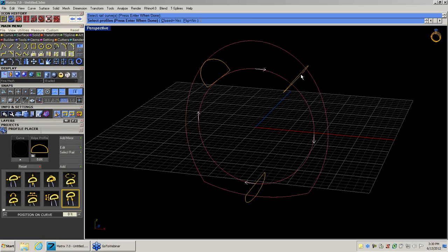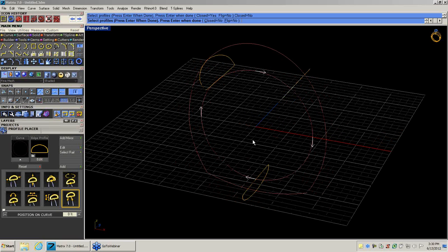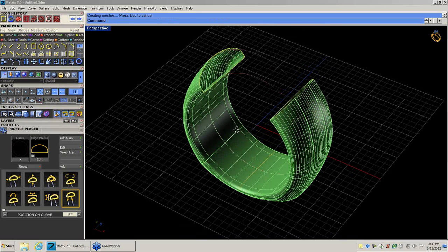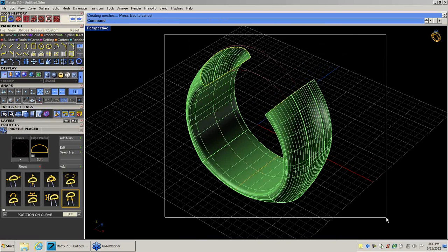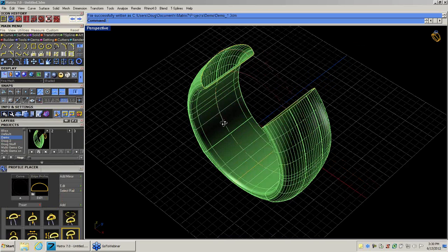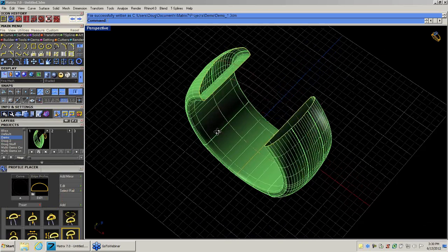It brings up these arrows, and then all I need to do is just click on the dots in the direction of the arrows. And the only conscious decision you need to make right now is, do I want this to be a solid band or do I want it to be open in the middle? So closed equals yes, which means it's going to be a solid band. I'm going to click it to closed equals no, and when I hit enter on my keyboard, I have now created a band. Okay? I'm going to take this while it's sitting here, and I'm going to drop it into my project manager just in case I ever want to come back and work with that again.